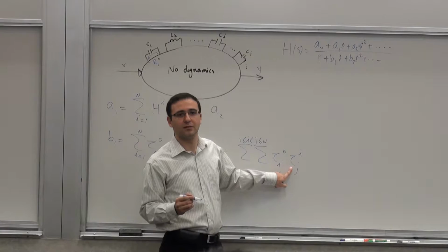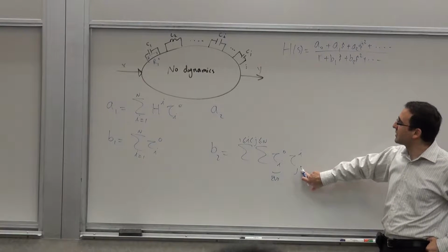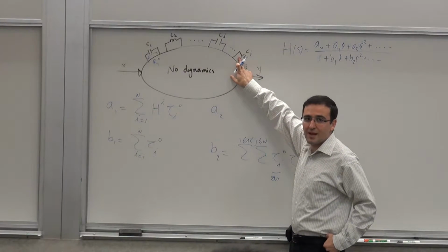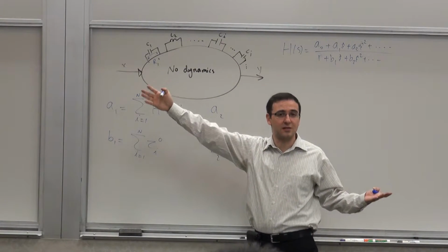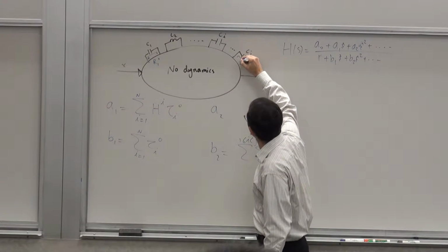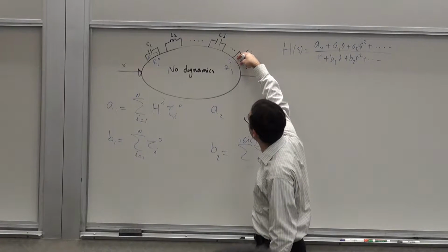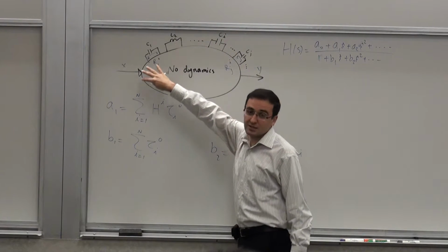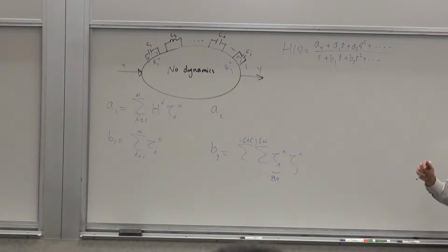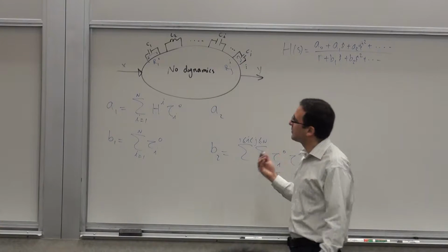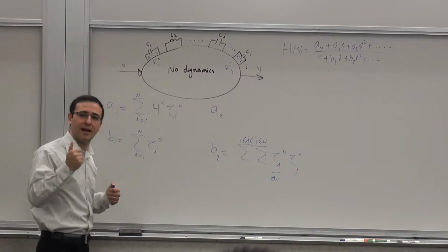Now these guys, we talked about them very briefly. What are these time constants? This is basically the time constant associated with the j element when the i element is infinite value and everything else is zero value. So this is a different low frequency calculation, a different resistance. That resistance you can show as Rji, which basically means the resistance seen by the j element when i is shorted. So this can be a different resistor. Now, remember, in our notation, one thing that makes it easy to understand is that any index in the superscript is the index of an element being infinite value.